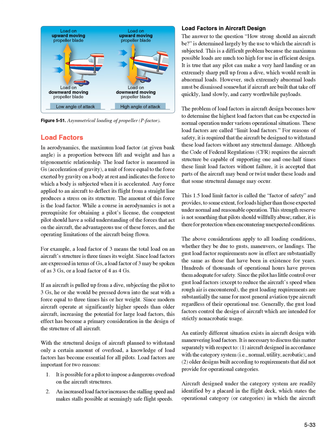Since the pilot has little control over gust load factors, except to reduce the aircraft's speed when rough air is encountered, the gust loading requirements are substantially the same for most general aviation type aircraft regardless of their operational use. Generally, the gust load factors control the design of aircraft which are intended for strictly non-acrobatic usage.